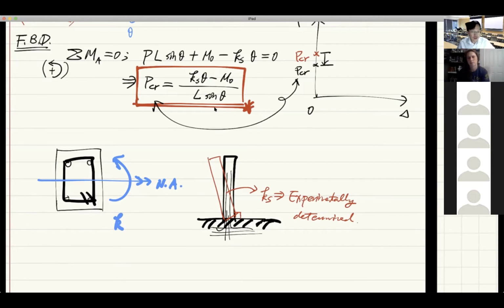Now, some of you have probably seen that from your work. You probably already know that there's no such thing as a rigid support. There's no such thing as a hinge support or perfect hinge. There's always friction. Friction is everywhere, right? And there's, of course, no such thing as a perfect roller support. Maybe something similar or close to it, but no such thing as a perfect roller, perfect hinge, or perfect fixed end. No such thing. Everything can always be measured or characterized by a spring constant. That's the reality we structural engineers must embrace.